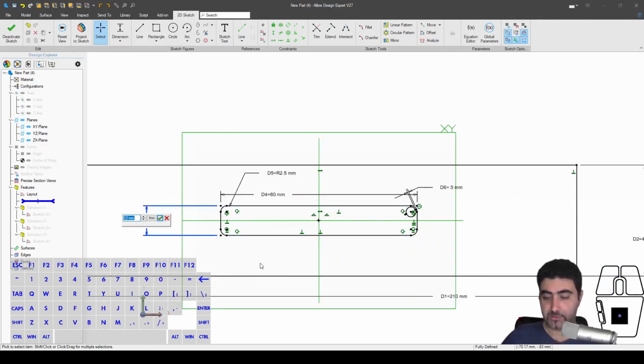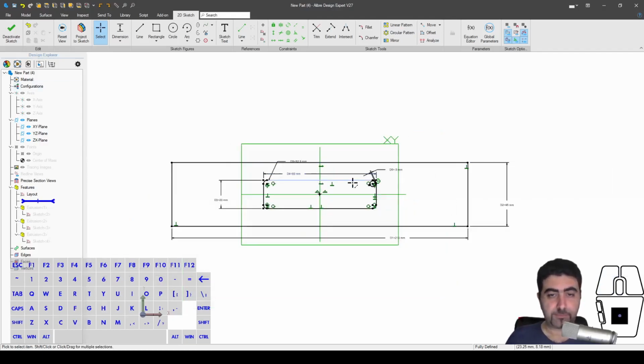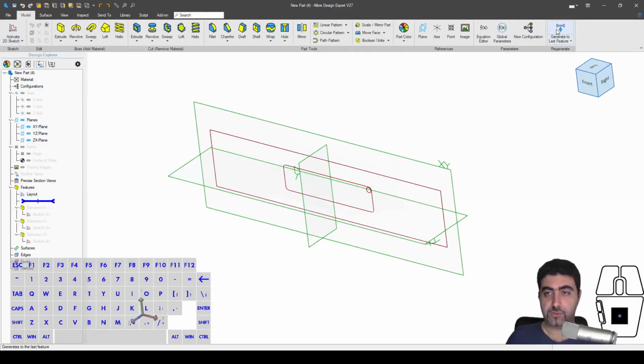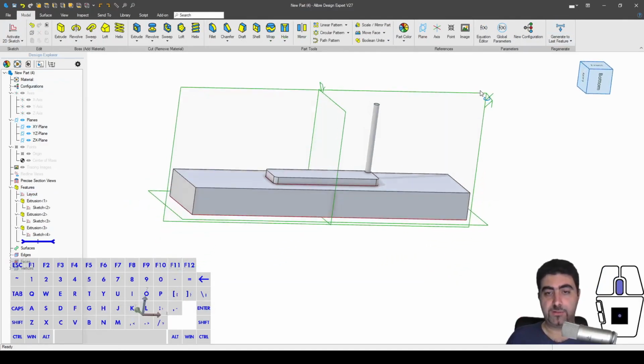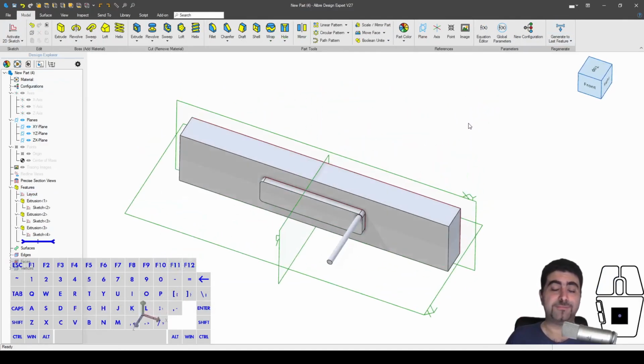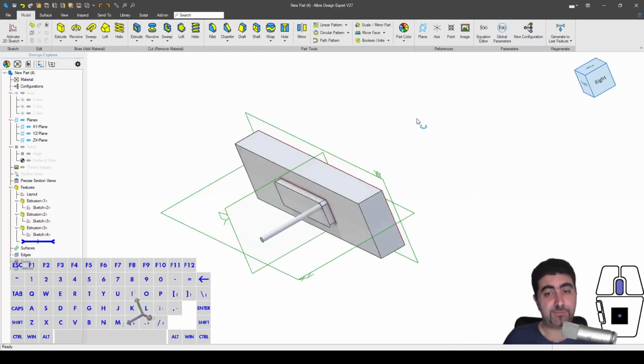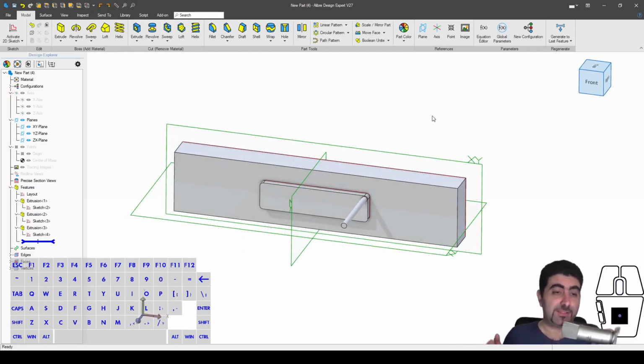I put there initially 220. Deactivate the sketch, generate to last feature. It is a layout sketch, it's following the initial layout. So that's how you would do a layout sketch in Alibre if you needed to. Some people swear by layout sketches. I find them redundant in 3D parametric CAD, but you know.